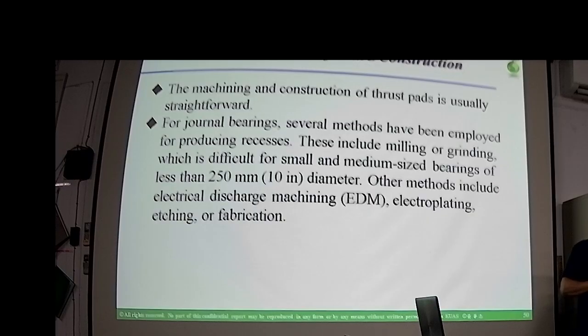For the air bearing especially, because the film thickness is small, usually a few microns to 10 to 15 microns, the precision and accuracy of the dimensions for manufacturing the component is very important.